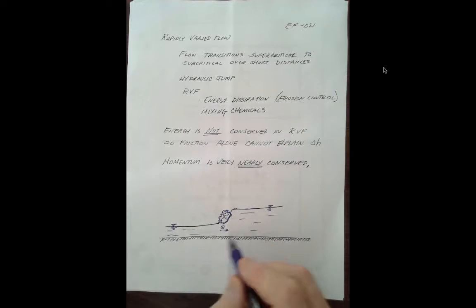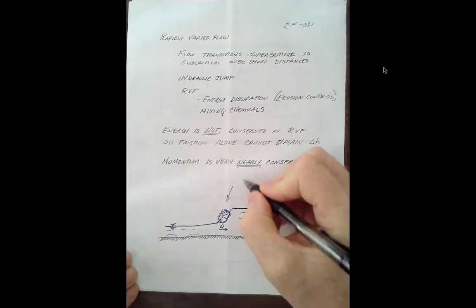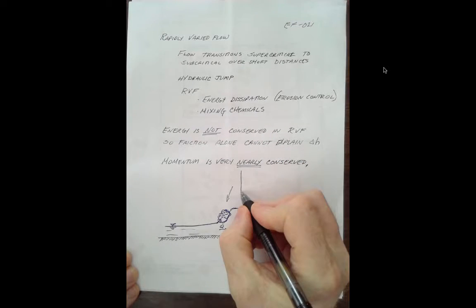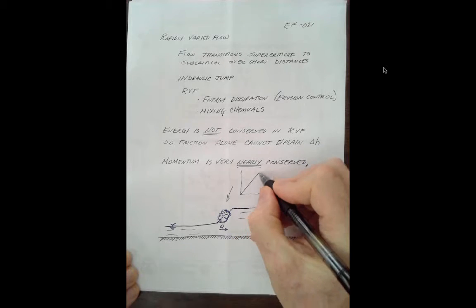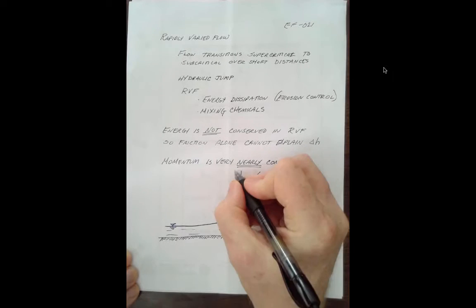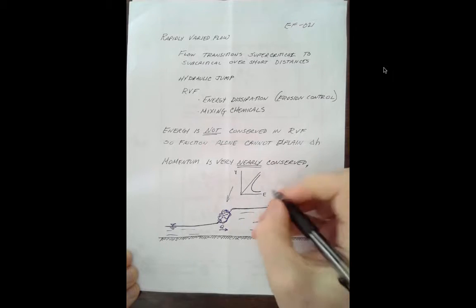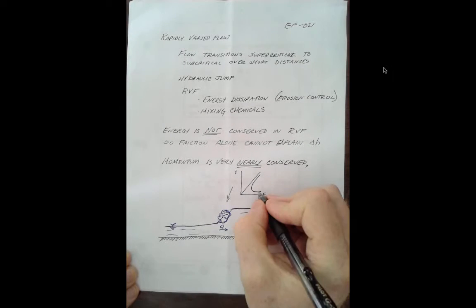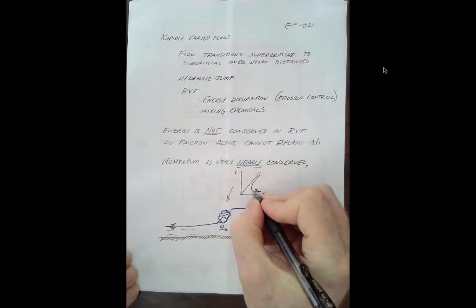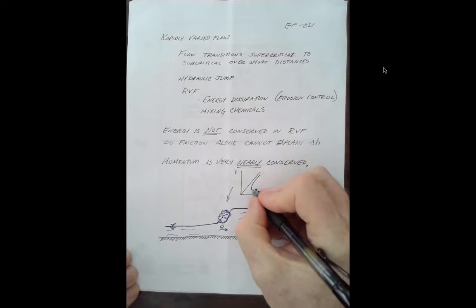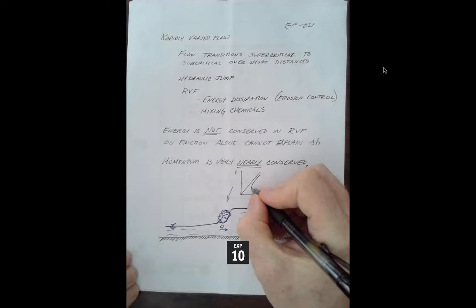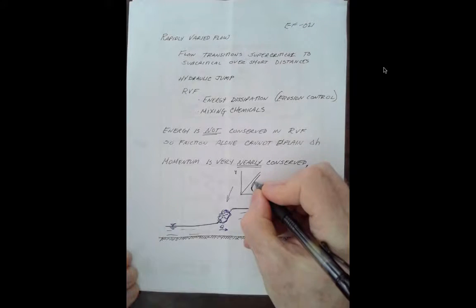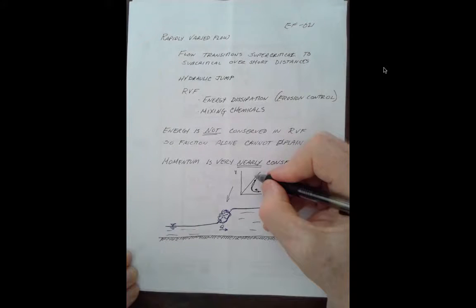So what's going on in this area is, if you recall our specific energy curve, what's happening here, at least conceptually, there's our energy, there's our depth, and it's on this line. This shallow stuff, we're down here, and so we're traversing this curve that way. And then at some point, pretty near or just past critical, the flow doesn't follow the line but actually jumps to a different step.